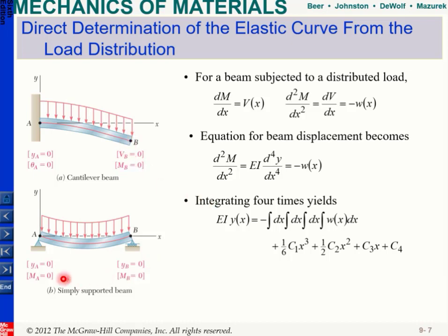So this time, in addition to my deflection or slope, I can also use, if I know what's my moment or if I know what's my shear force, to get these constants, okay? So I need to determine them from the boundary conditions. So what we will do is we will solve some more examples and we will try to understand how we can find our elastic curve for the questions that are given.